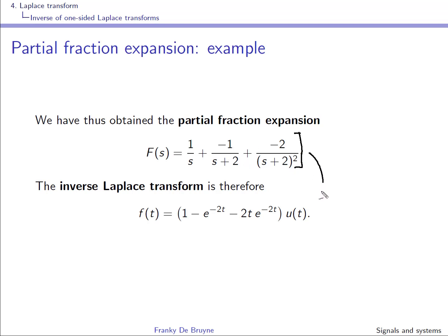So now we have to take the inverse Laplace transform. The inverse Laplace transform of 1 over s is a unit step. So here we have an exponential multiplied by this unit step. Please do not forget the unit step, to make sure that the function becomes causal. And now we have to take the inverse Laplace transform of this one.